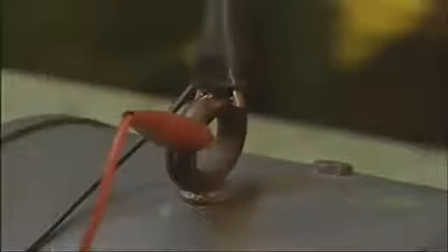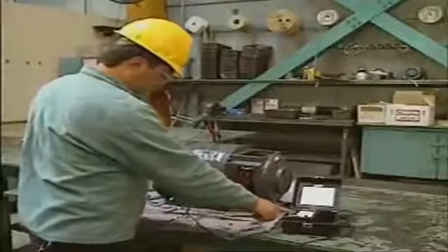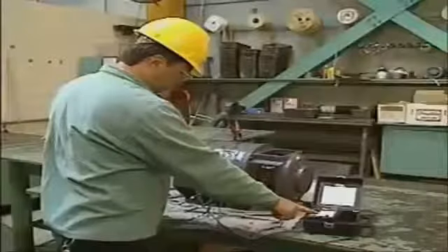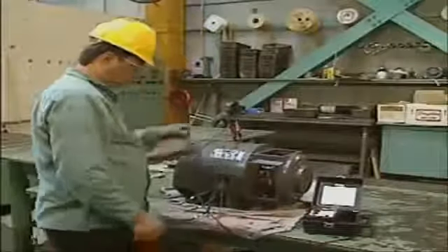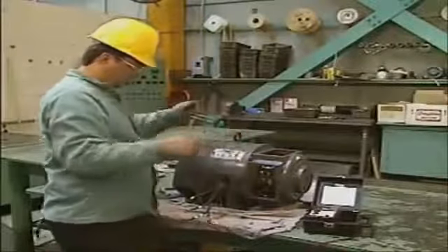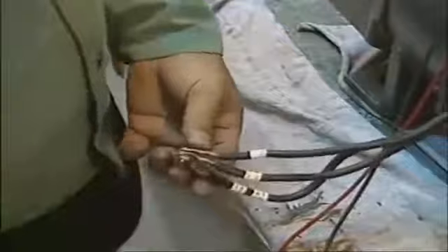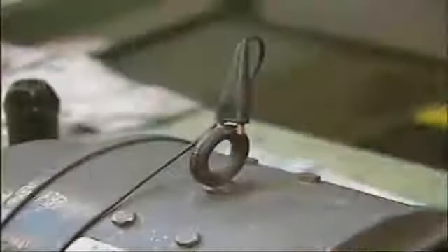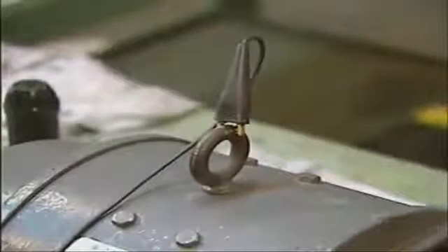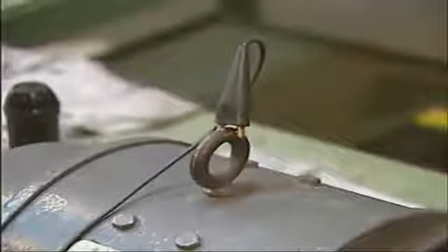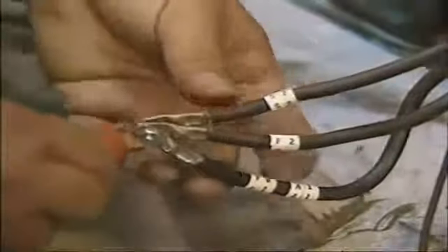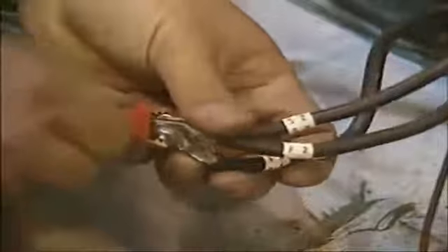Finally, connect both probes to ground and operate the meter. This time, the meter should indicate 0 resistance. If the meg-ohm meter is operating properly, it can be used to test the de-energized motor. First, the motor's 3 leads are connected together. Then the meg-ohm meter's ground lead is attached to a metal section of the motor, and the meter's line lead is connected to the motor leads.